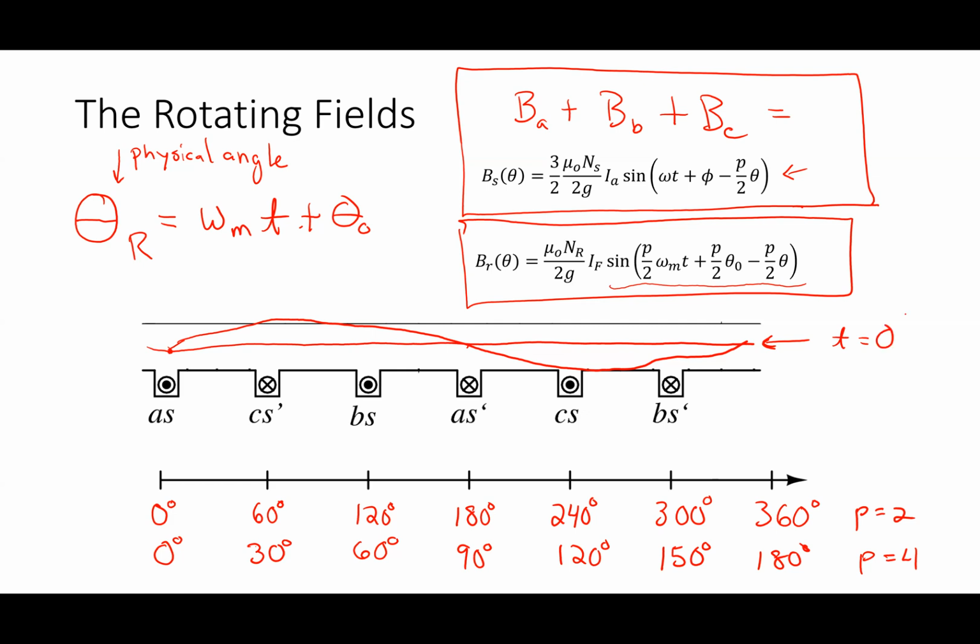What happens as time advances? What does that field do? The phase shift. The field basically phase shifts, right? Because we said what's going on is the field is moving. So in terms of the air gap itself, it's rotating around the air gap. It basically means from this picture here where I've drawn it out lengthwise, the field would move over time, just keep shifting. Okay. So how fast is this guy moving in time? So the stator field, how fast is he moving in time?